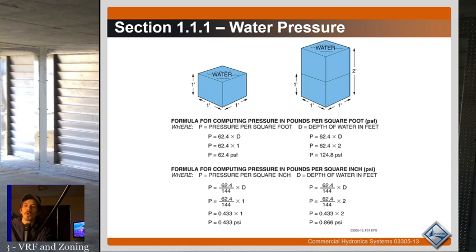So don't worry about the weight of the water when we're talking about feet of head and things like that. It doesn't matter how much the water weighs. It matters how tall the column of water is. And for every 10 foot of that column of water, it'll be about 5 psi. And that's how we use manometers.